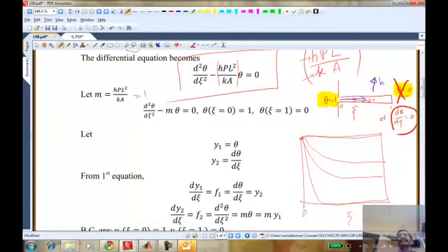It's the same temperature as surroundings. It's the same temperature everywhere. That means you make H equal to 0. That is, you're not taking any heat out, and you're putting heat from the left, so it's going to heat the entire fin to the same temperature as the base, and nothing escapes. Right? And that's possible. But it must satisfy on the right side: if you take the derivative, in all these cases, the derivative must be 0. On the left side, the function must have a value of 1. So these are all the possible sketches that are possible solutions.